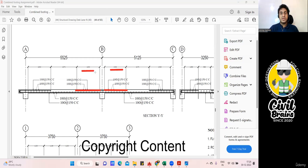If I add 1650 and 1550, will I get the cutting length? I'll get. But the problem is in the middle. In the middle, you have a beam and the width of your beam. So you have a beam here in the middle. And the width of this beam is how much? 300, because beam width is 300 everywhere. So you'll be adding 300 also. So what will be your cutting length? 1650 plus 300 plus 1550. If you add everything, you'll get the straight length of this bar.